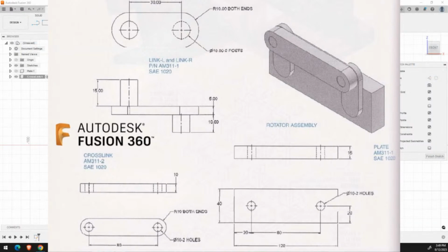Very simple. You can use line to create an arc, like our practice earlier. From the straight line, just click. If you want to make an arc, click and hold. Then click and hold again. Then just two circles, and apply equal, and then dimension. And we can now make it 3D. So just finish sketch.